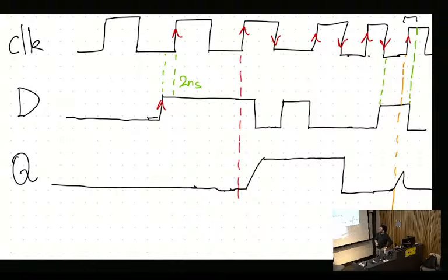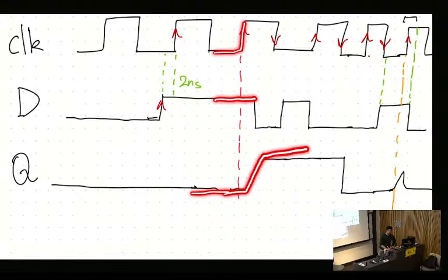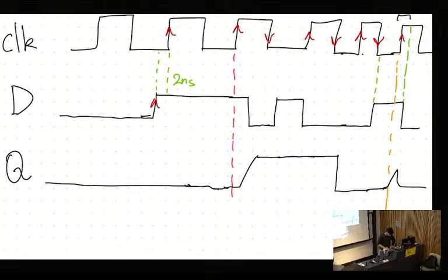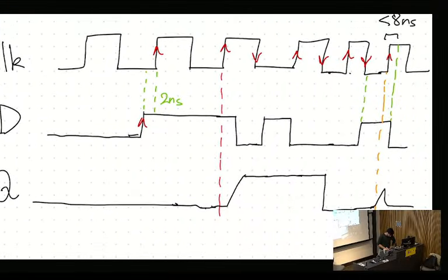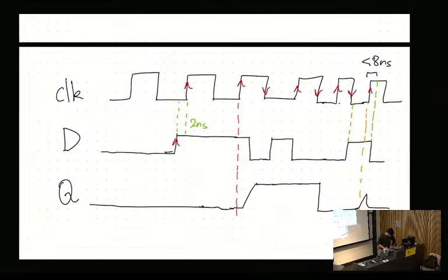So now it goes high on a clock edge. The clock edge goes high, the output was low, and the input was high, and so it latches onto the high as the clock flips. I think that was because I redrew the clock signal, unfortunately, differently to what I drew before.